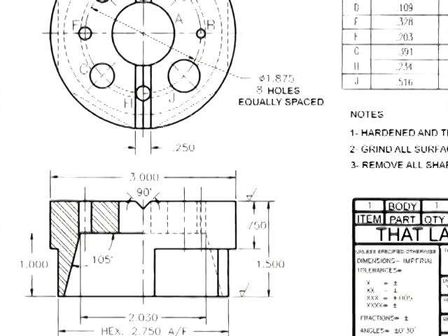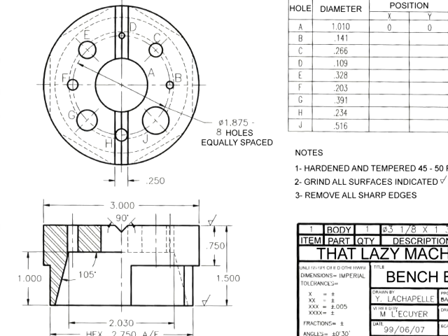And if we come back to the rest of the drawing, well, we notice something that's a little bizarre. There's no section line in the front view. And that's okay because if what we're looking at is clear and obvious, well, no section line is required. In this case, it's a half section. And half sections rarely require section lines because when we look, in this case at the bottom view, the direction of view is clear and what has been cut is also quite clear because we can see both sides.